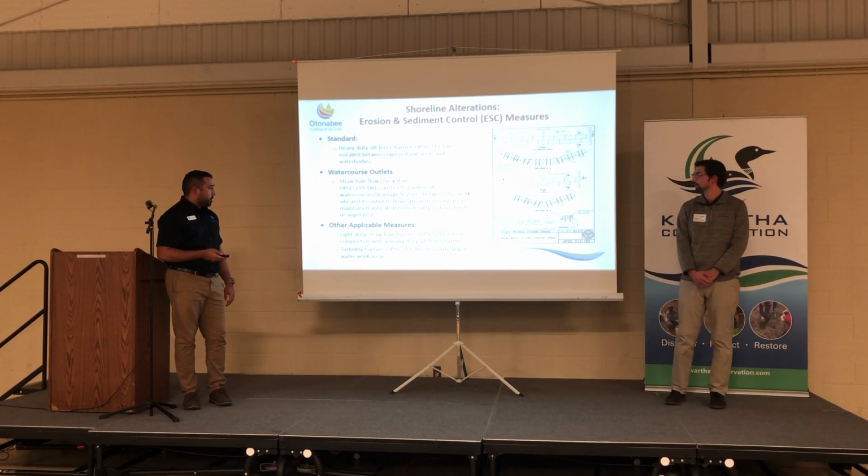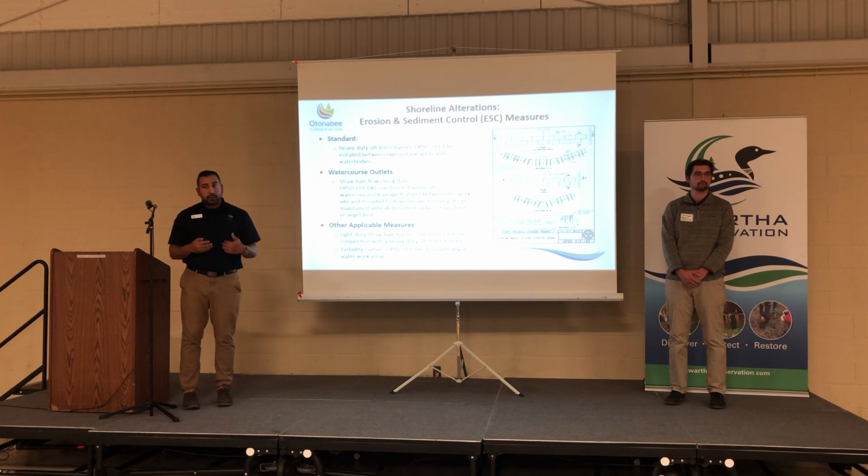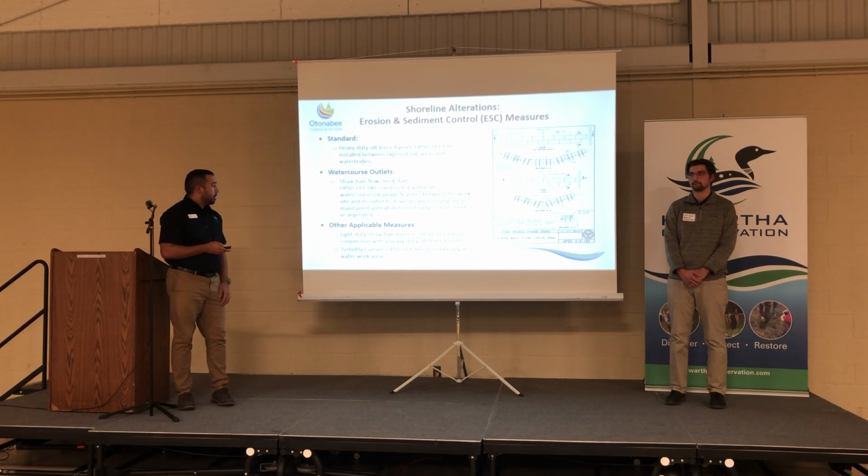Some other applicable measures that we tend to use quite often are light-duty straw bale barriers. Those can sometimes be used instead of silt fence barriers, or they can even be used in conjunction. So you can have a multi-barrier approach there, with the straw bale barriers butted up against the silt fence barriers.